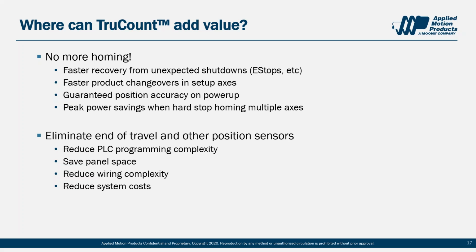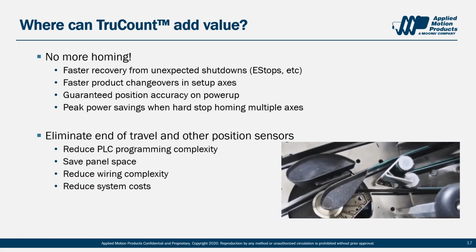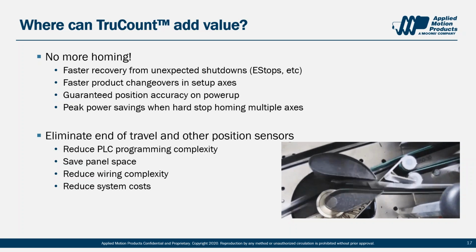I want to talk about that last one for a minute. I had a customer who had a massive sorting machine that used about 200 axes as diverter motors, like this one. On startup, they were hard stop homing all 200 axes at the same time.